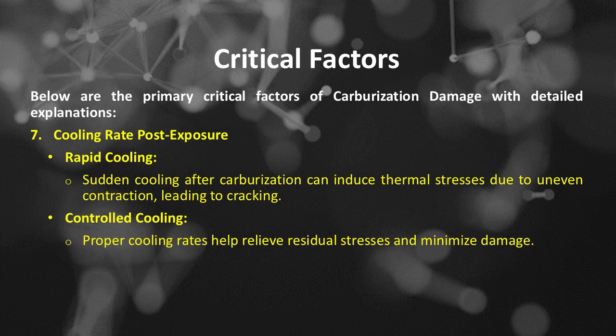Number 7 of primary critical factors of carburization damage with detailed explanations is cooling rate post-exposure. Rapid cooling, sudden cooling after carburization, can induce thermal stresses due to uneven contraction, leading to cracking. Controlled cooling: proper cooling rates help relieve residual stresses and minimize damage.